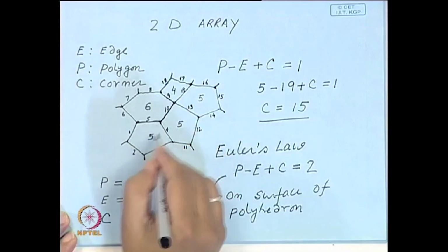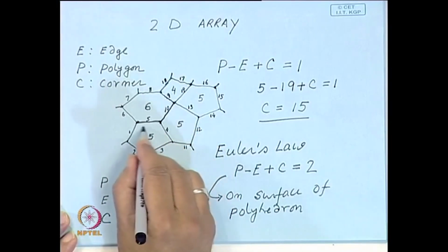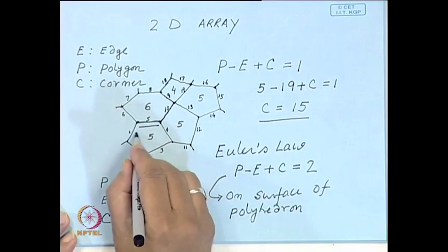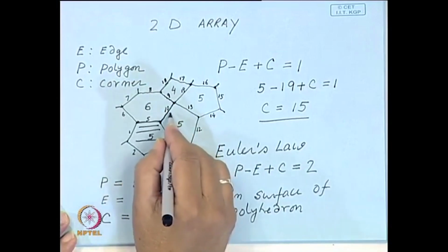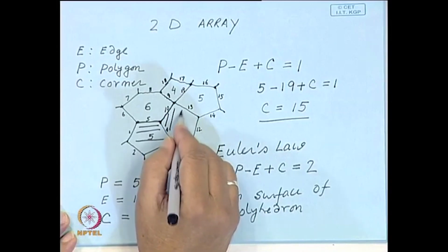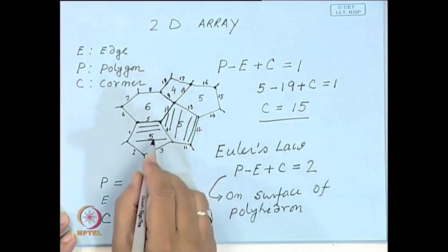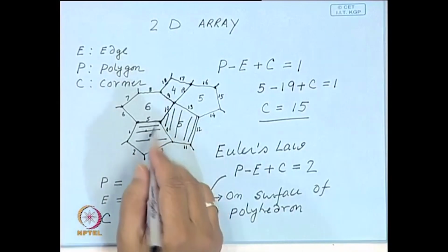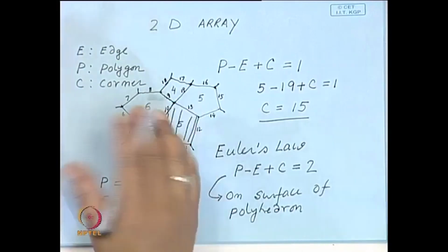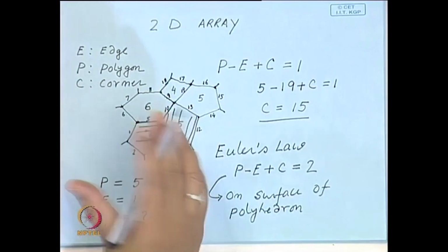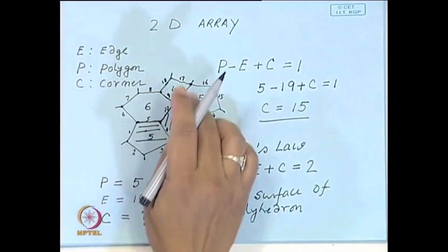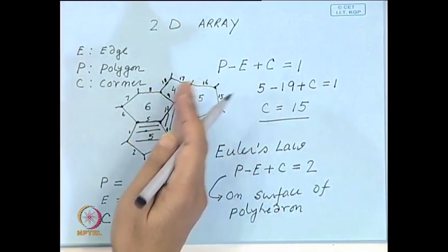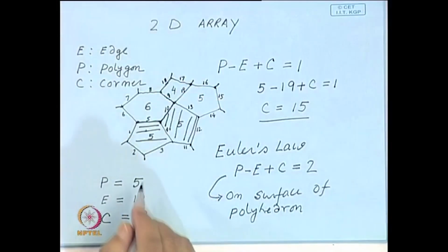They meet each other. So, this will have one crystal arrangement, say here these planes are arranged like this. Here possibly the planes are arranged in a different way. So, if you move from one grain to another, the periodic array, the crystal structure, is still the same, but its orientation is different. The same planes are oriented differently.